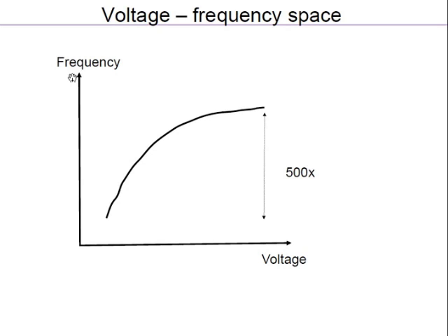So what we saw is that the frequency as a function of voltage has a shape somewhat like this. As you increase the voltage, frequency goes up, and you can imagine there is a certain saturation. There is a certain max frequency you will achieve, and there can be quite a bit of play available here. That means you can run from a gigahertz down to megahertz, based on what voltage you run. Of course, you have to make sure your circuits will run at slow speeds also.